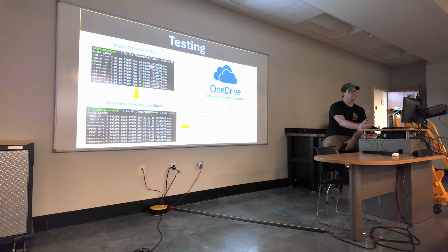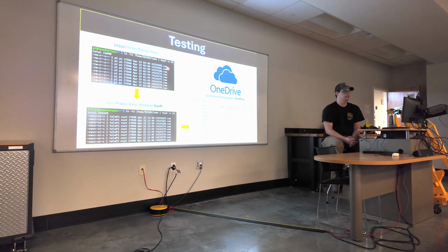When the file name starts with a 1, that's actually FAT system 2. It starts with 0, that's FAT system 1. And it's basically lining up these file names, which is actually just a date and time code. So what it would do, you go through there, look at the file names and say, okay, I have a 0 file that ends in 282, but I don't have a 1 file that ends in 282. So then it would just either quarantine or delete that extra file, so to speak. And if it's just one file, you'd be missing out on just 15 seconds of data. If I had something running on the system and something went wrong, it could be deleting days.